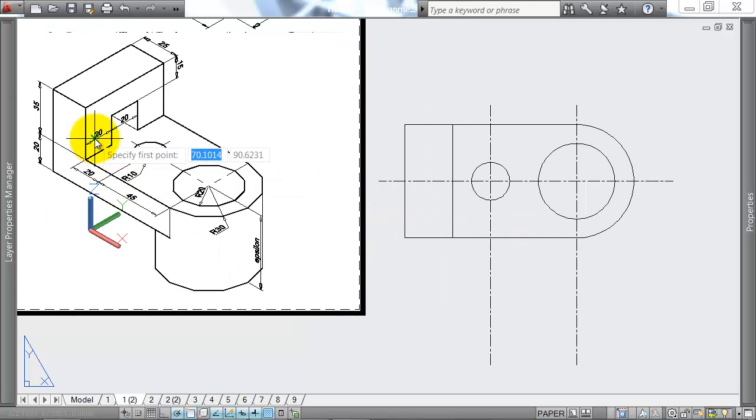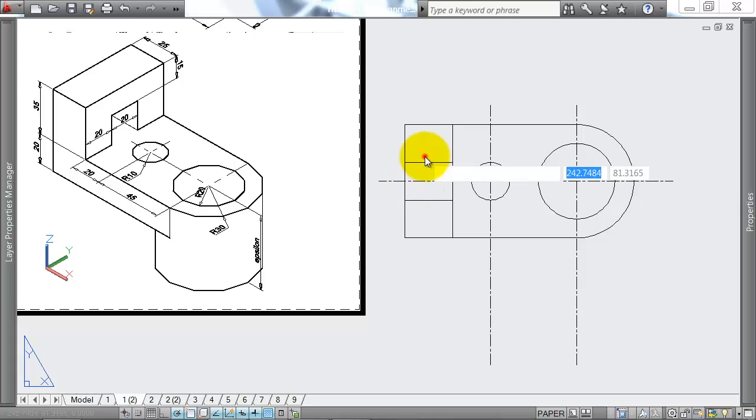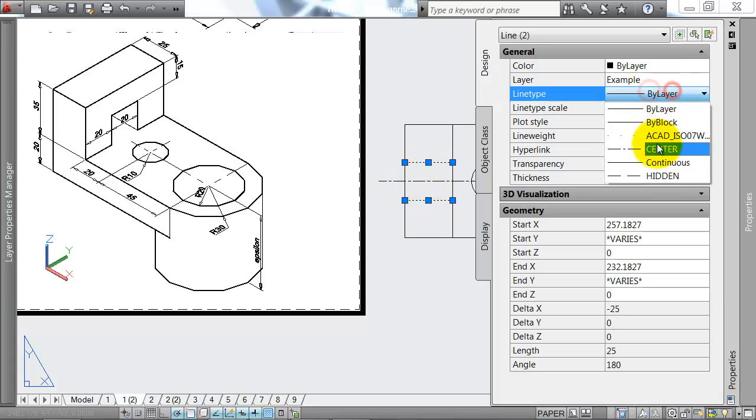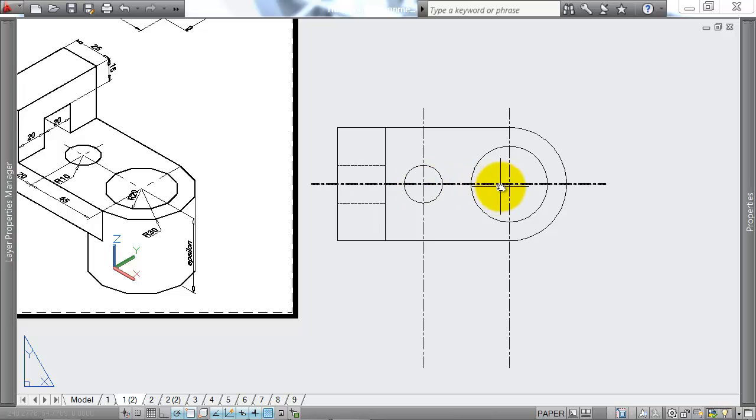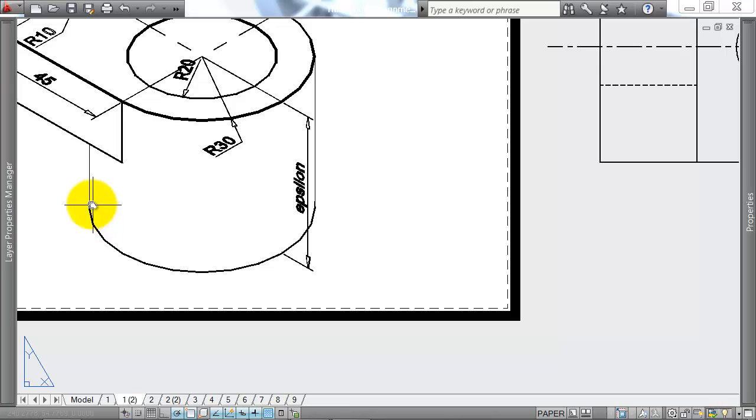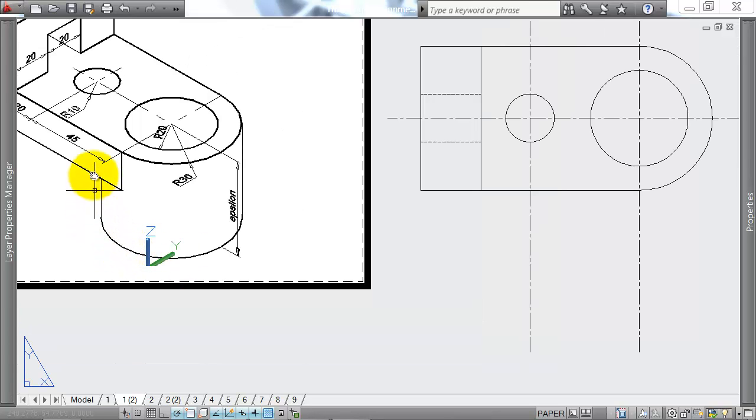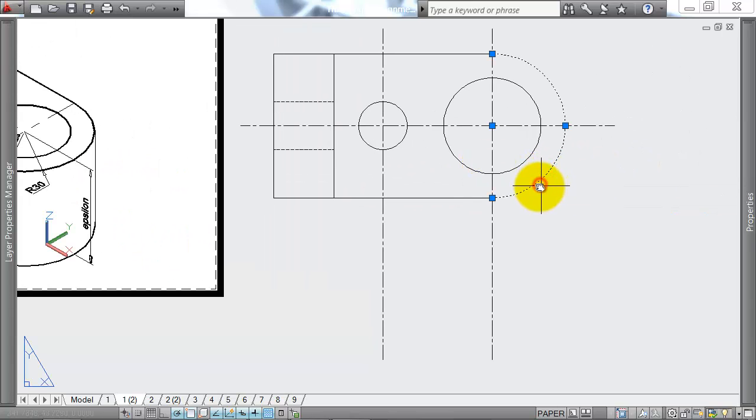In terms of hidden lines, I've got one hidden line which is going to show up this internal part here. That's going to be 20 units from an edge and across. And similarly on this side, 20 units down and across. So this gap in the middle should be 20 units. Hidden lines. Okay, now I mentioned earlier that because this is a cylinder under here, you'd actually have a hidden line that follows the cylinder around the inside of the shape.